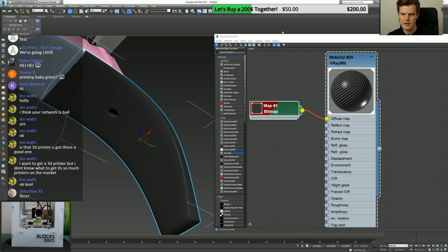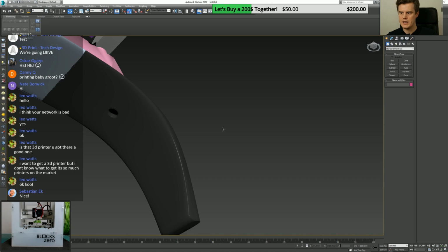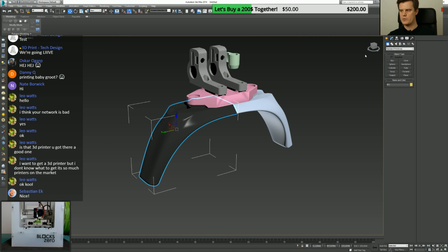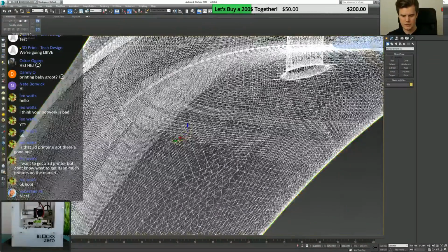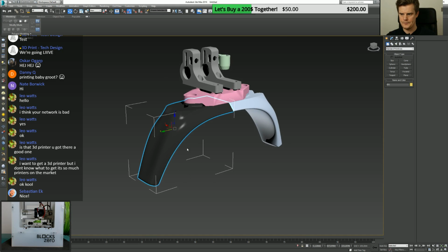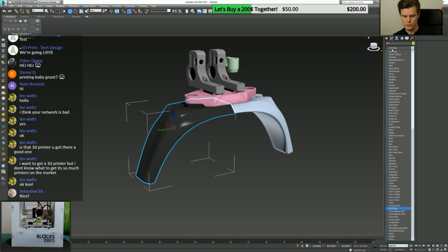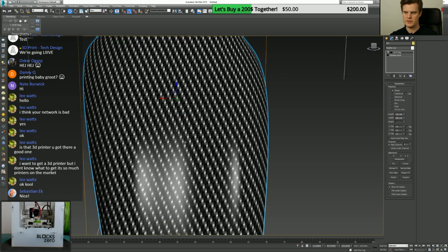And the reason for that is that when we do models in Fusion 360, they rarely or almost never get any sort of coordination, which means that all of these small triangles are not linked together. There's no way of putting an image on these polygons. So we need to use some sort of tool that is called UV mapping. So if I just apply this modifier, we can start seeing some of the results.